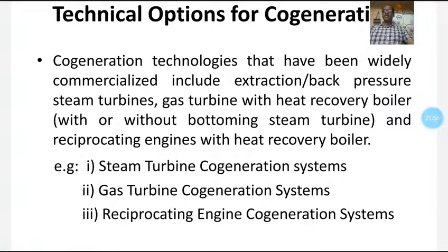Now, what are the advantages we are getting? High electrical efficiency up to 40%, high total efficiency, that is overall plant efficiency, up to 80 to 85 to 90%, and extremely low emissions due to the use of clean natural gas in combination with the lean burning concept.